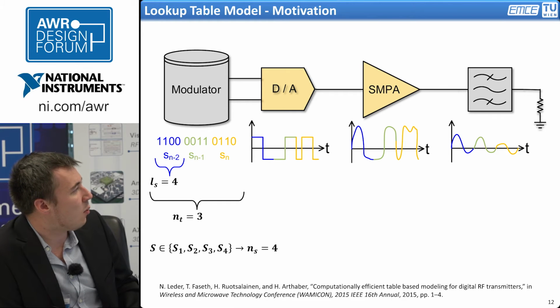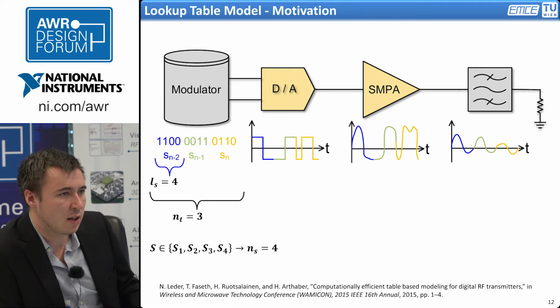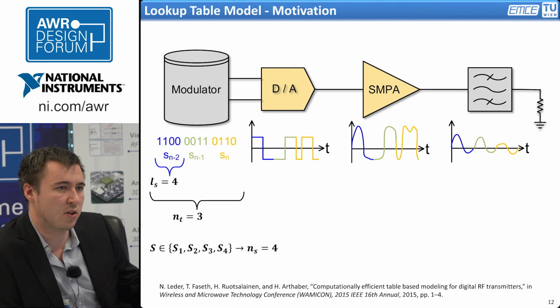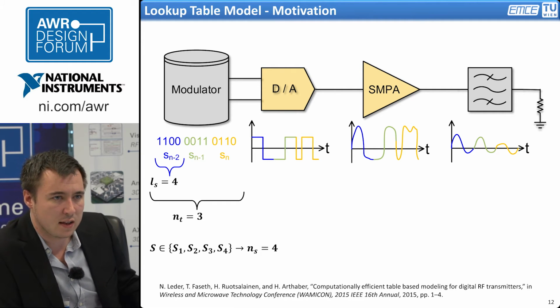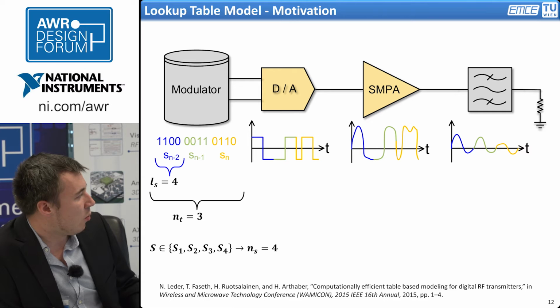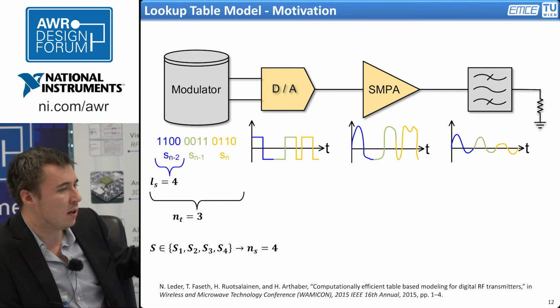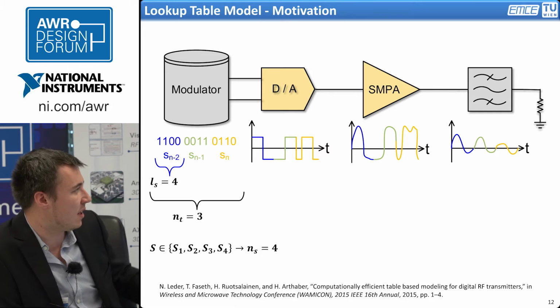The moment we are here at the amplifier, between the reflective filter and the amplifier, actual load modulation causes precursory symbols to affect the current symbol. So a kind of nonlinear affected delay is introduced, which breaks this one-to-one relationship. On the other hand, and this is the good news actually, we still can address one of the sub-waveforms by considering a much longer excitation sequence in terms of the symbols.